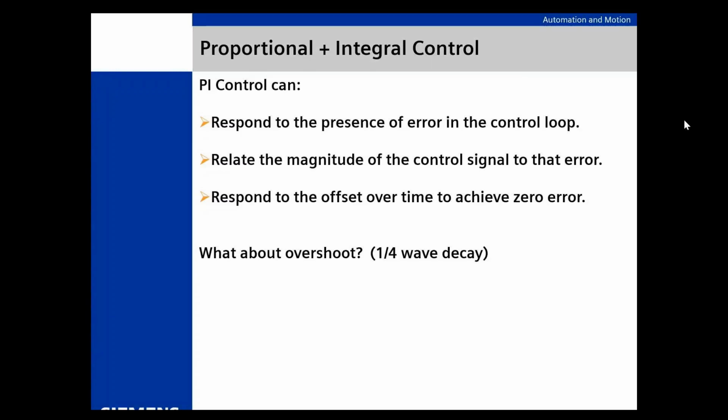derivative. It's not 0, it's something. Well, that's fine. Most controllers now that have any sophistication, most of them do, only turn the derivative on if they need it. It may be there, it might not be 0, but they don't always use the derivative. Why? Well, they don't need it. They don't add that complexity. They don't add that processing time because they just don't need it. Okay? Most of the loops out there are proportional integral only.